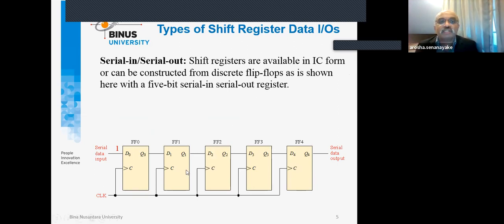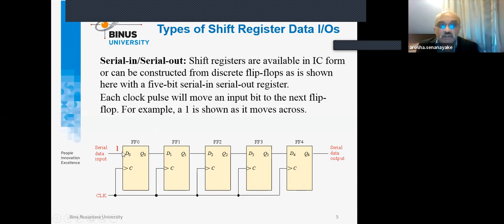at a time. So then actually here you can see data entered is 1, and at the same time data transmission will occur when, oh, very important, an additional element involved in sequential circuits, as you remember very well from previous lectures, is based on the clock. So in this case, you can see that the clock is connected to each and every D-type flip-flop. So that really, with one clock pulse, what is going to happen? This one will move to this as input to the second one.